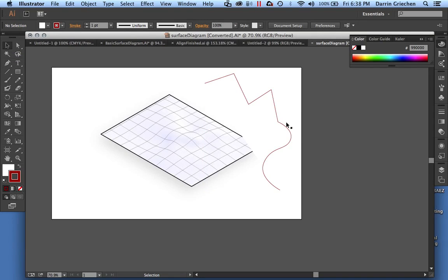And you can see that we created this. And you can also see that I didn't turn off my fill, so it's trying to close this shape and fill it in. So to fix that, I go over here, click on the fill once, and then I click down here, none. And, oh, we got to select that item first. Sorry. Click, and none. There we go. All right. There we go. We don't need that.